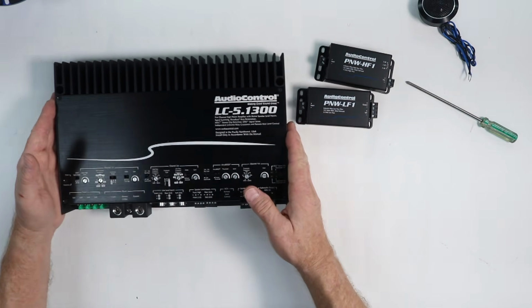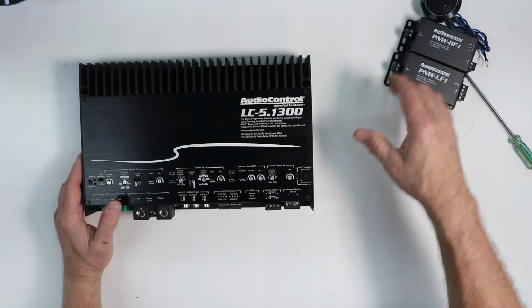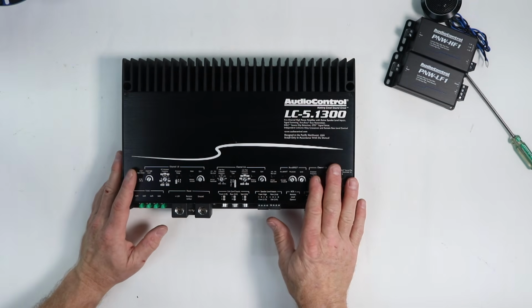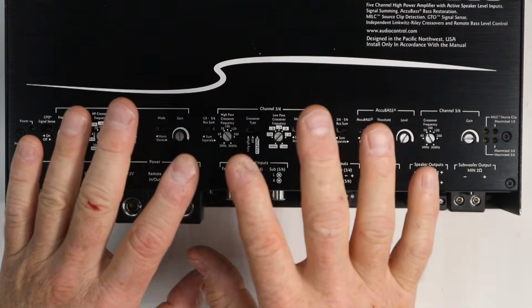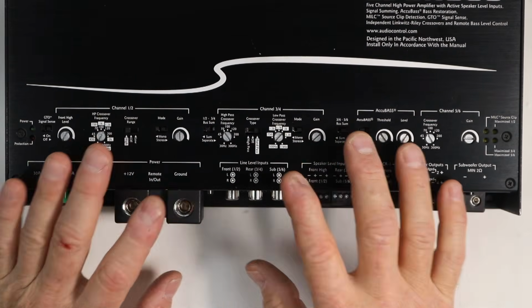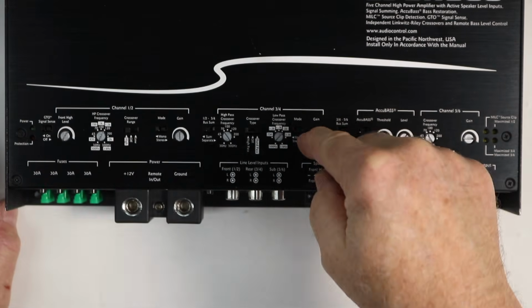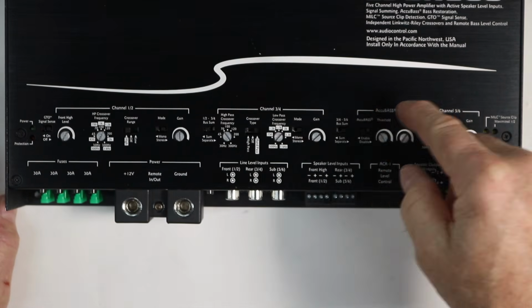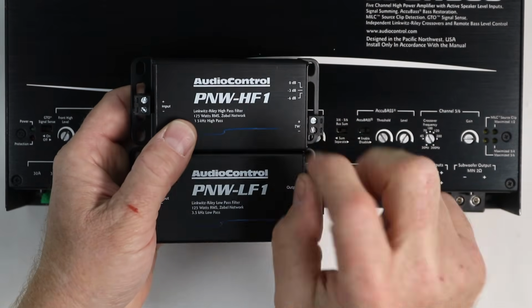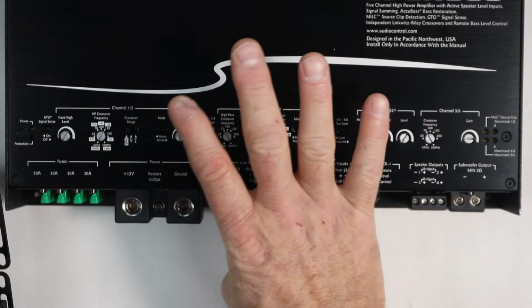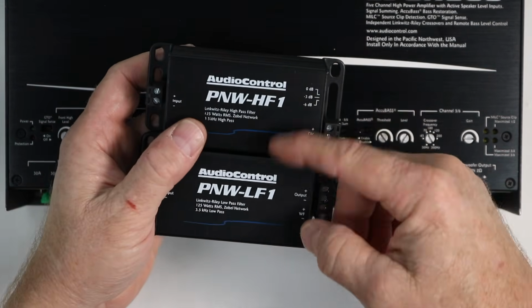Let's talk about the active side of it done in the amplifiers, high pass or low pass, that we're so accustomed to adjusting. When looking at an amplifier's active crossover, you say, hey, I want to run a set of tweeters and a set of mid-range. Well, that's going to mean we're going to need something like this if we have 2 channels to run them on. Well, let's say we bought a 4-channel amplifier. We don't want to use these.